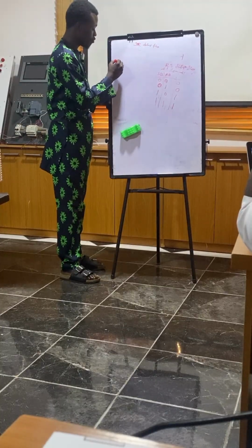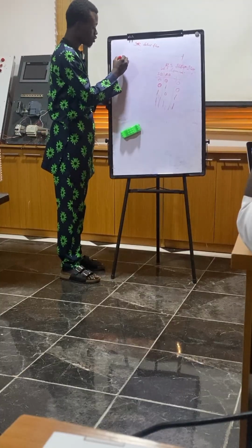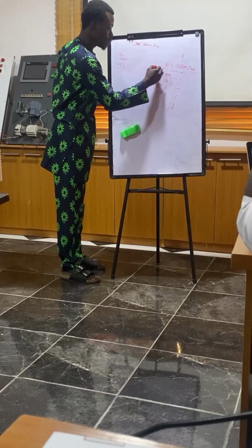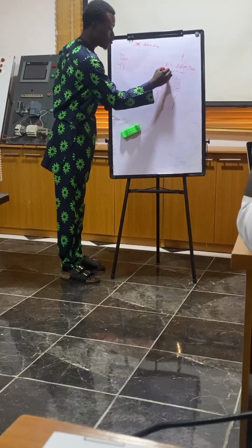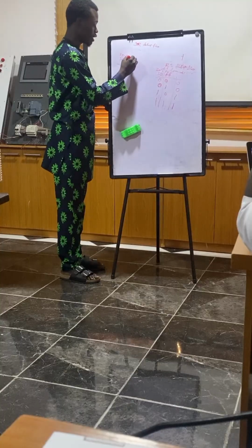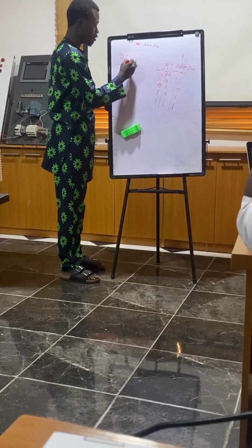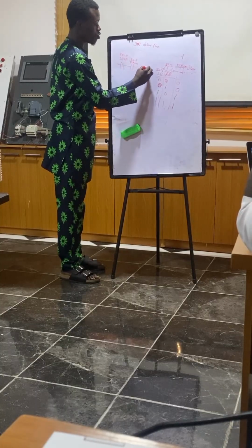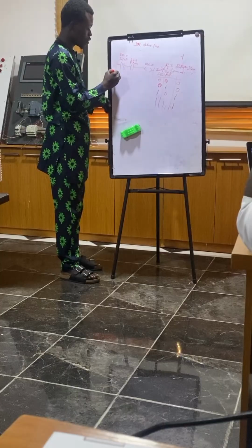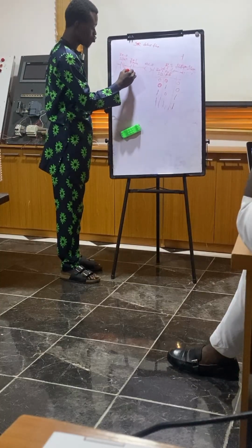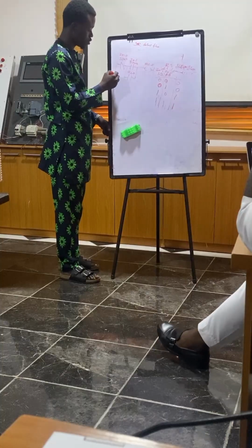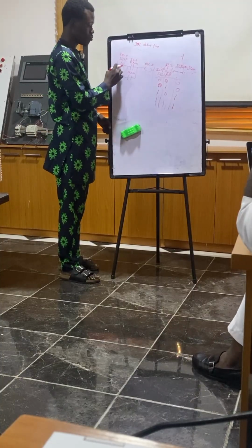So I still have my normally closed stop button, the I0.0. So this I0.0, am I correct? Then my start I0.1, and then your output, let's say Q2.0. All right, and then the latching that we have here, Q2.0. Are we together? So now this is for SR.